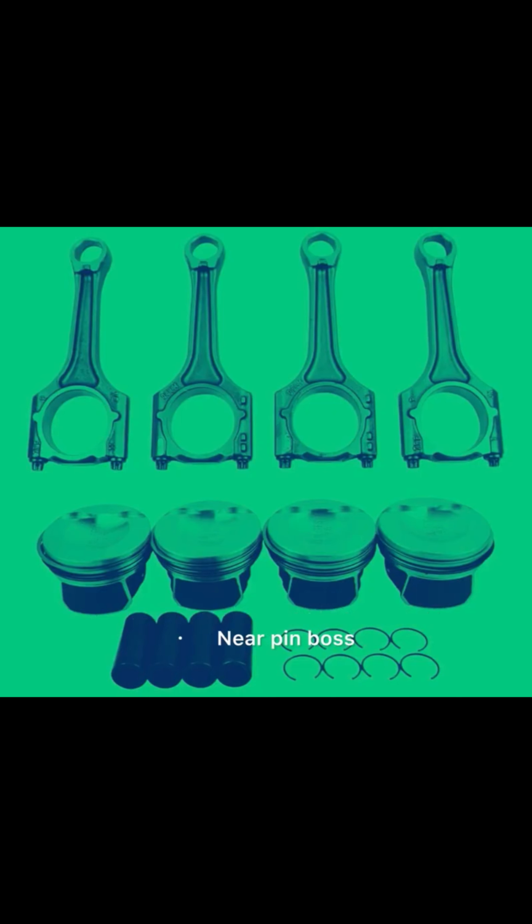12. What are torsional twist rings and how do they work? Have a bevel that is acted on by combustion gases. Twist up to seal against combustion. Reverse, twist down to seal, scrape oil.